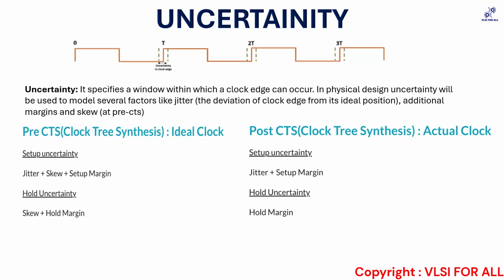So understand that a hold uncertainty value of 0.1 ns and a setup uncertainty value of 0.05 ns is not possible. If you're not believing me, open up the timing report in your design and have a look at it.